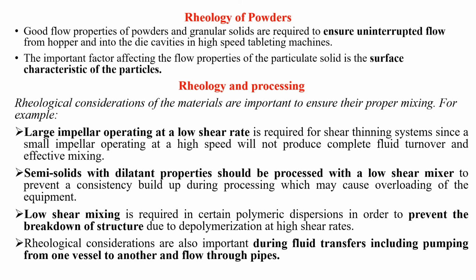And again, the most important case is when we are mixing polymeric solutions or polymeric dispersions. If we run the mixing unit at higher speed, higher shear rate, there is a chance for these polymers to undergo breakdown at the molecular level because of the shear. This results in structure breakdown.